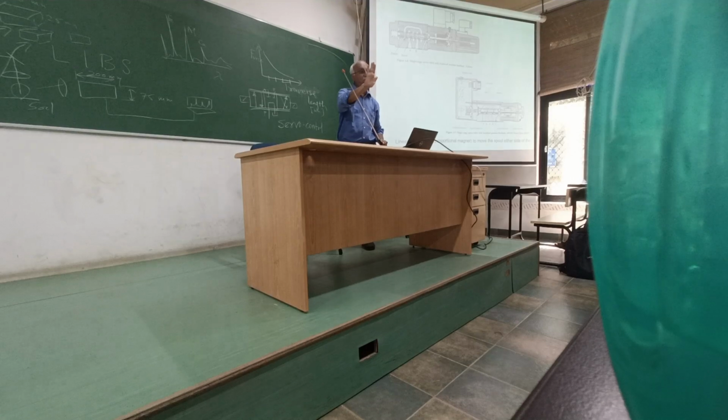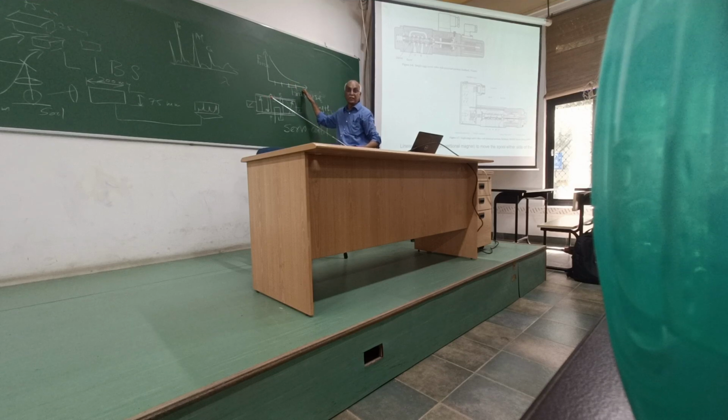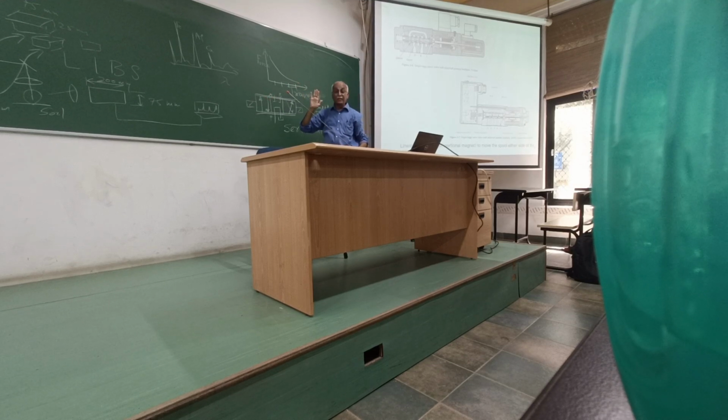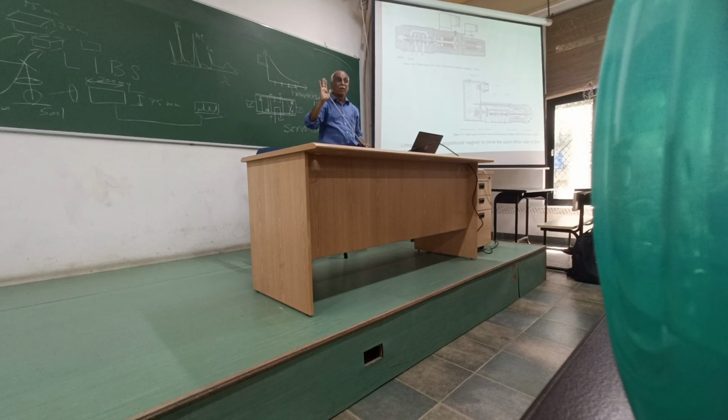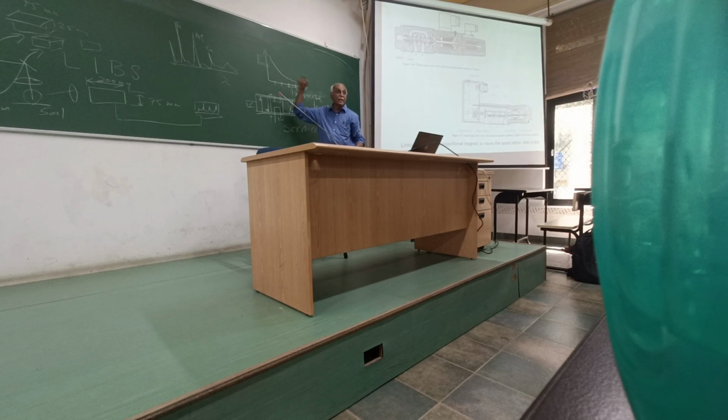The driving force for this spool using solenoid operation decreases exponentially. It's not linear. As the spool starts moving, the force acting on it decreases because of the solenoid configuration. Hence this is not a correct way to control, because we always have to consider position and the corresponding change in magnetic field and current, which will change non-linearly. So it is not a very easy way.